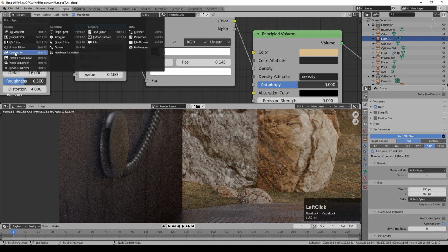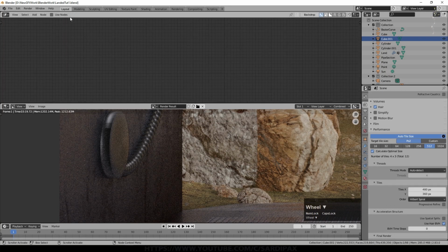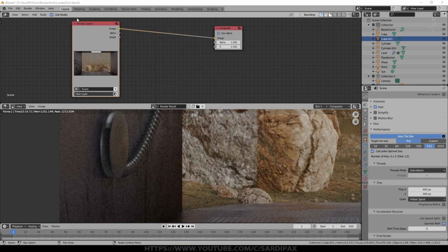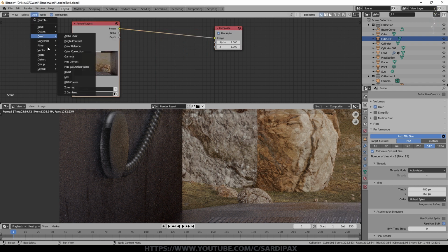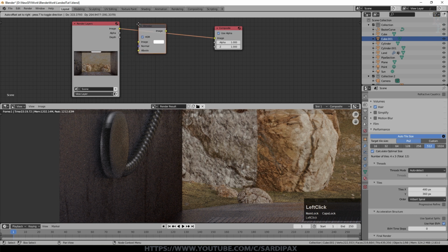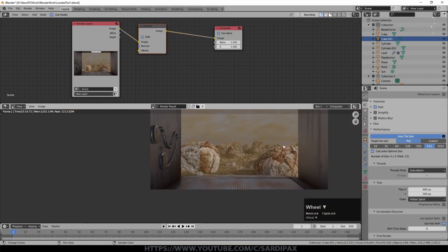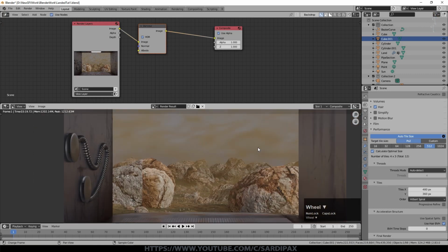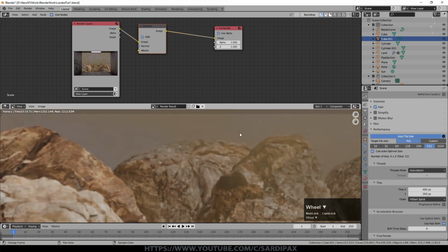So we'll change to the compositor up here, and we'll say use nodes. I didn't do too complex a compositor. But the first thing I'm going to do is just add under filter a denoise node. Now by default, just adding that node in, you can see it's compositing away. You can see it's smoothed it out already. And you could just do that and you've already got a very smooth looking image. If that's what you want, you can see the noise is just basically gone.